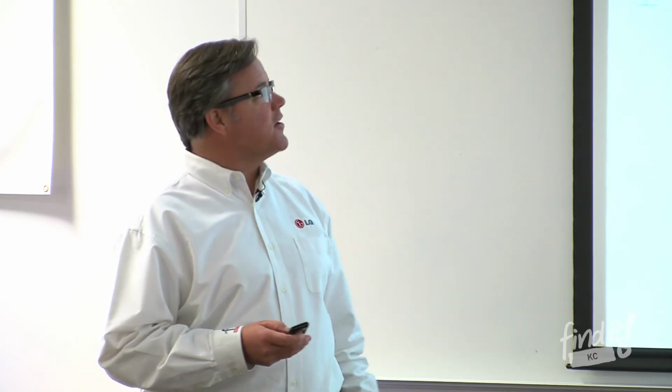To your question, okay, that's awesome. It gives us this heat, but how much is it going to cost me? Okay, so this is from AHRI. This is efficiency. Okay, we see that we're in the 2.5, 2.4 efficiency rating when we're talking about tonnages, different sized units as you go across here. And then this is the COP, and this is these units operating at 17 degrees.